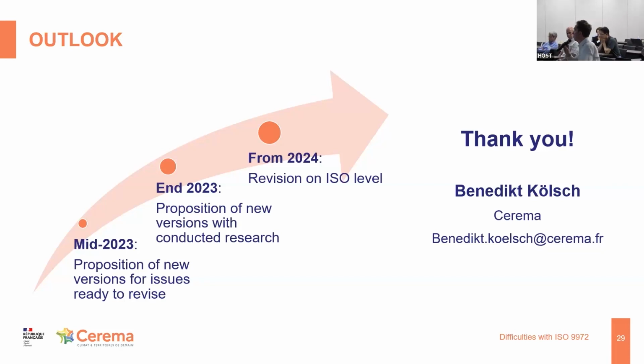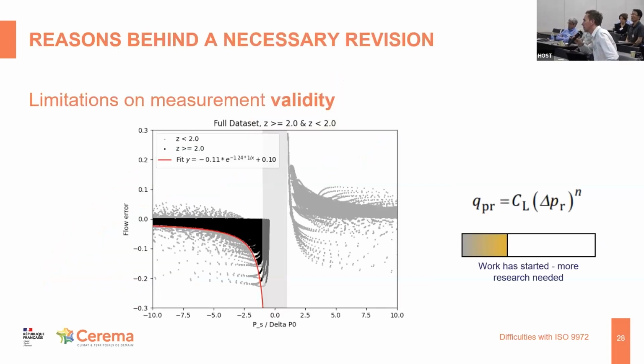Thank you for this overview. Just for clarification, in the final error calculations, the simulations that you showed, the zero flow pressure, does it include the effect of wind and stack effect? Indeed, not stack effect, but wind. The stack effect is not included yet in the calculation.